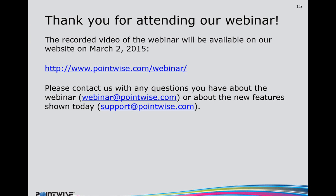There was another question about orientation. This is tied into align to surface, which allows you to also specify that orientation. The question is, does the orient display normal originate from the origin? It's a little bit more complicated. The normal is actually defined as the center of your view, so that center can actually move based on the current view that you have. It takes the centroid of that view and uses the normal that you enter in that panel to set the view from there.